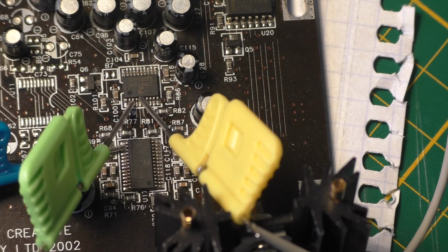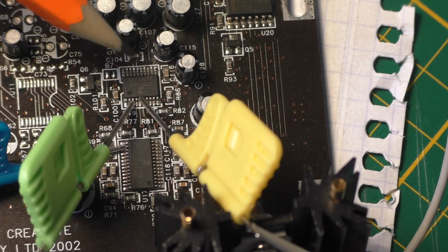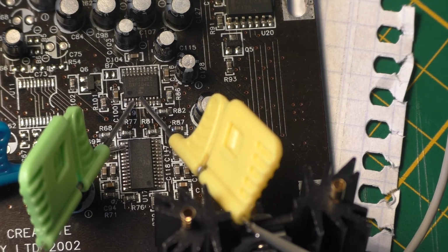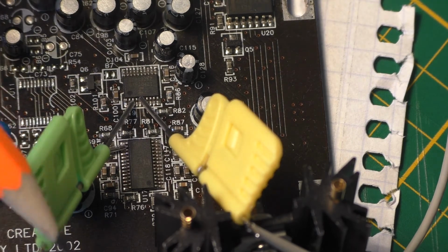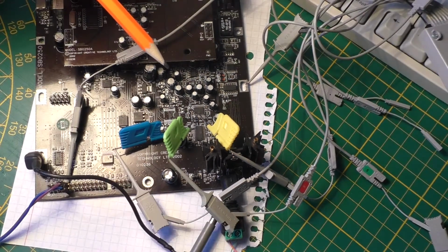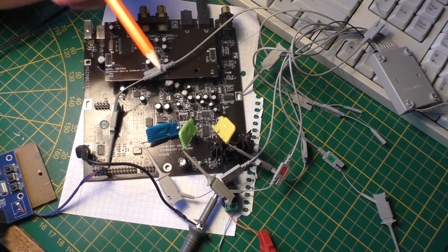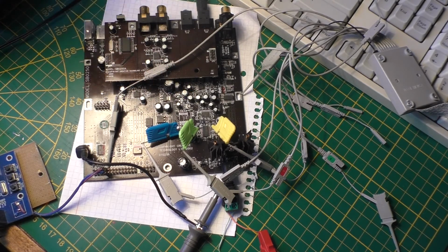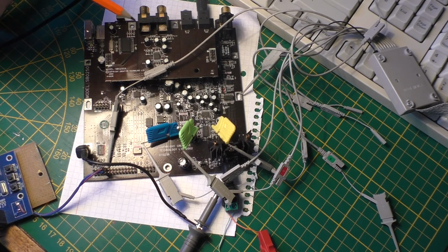There are no test points, so I had to break out these fancy cheap hooks, because this is so fine pitch that even the regular easy hooks from the logic analyzer were too big, so I have it connected in like 2 steps. And despite the name, I2S is not related to I2C, it's more like an SPI with an extra control signal.